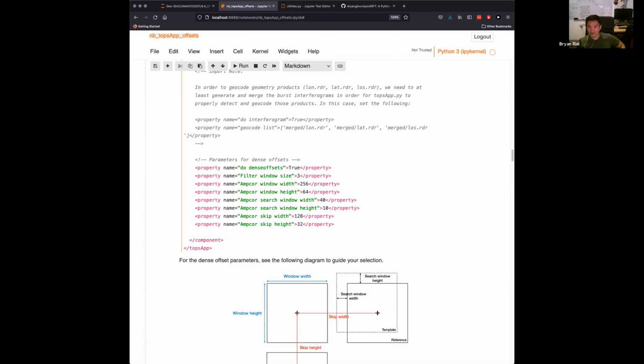What is the approximate? So the vector orientation for displacement is essentially just 90 degrees from your look direction in range. So if you look at your heading angle, that's essentially your azimuth orientation, and you can say your incidence angle is essentially flat along the surface. So that would be a 90 degrees incidence angle. That's one way to synthesize an azimuth look vector from look vector components that you have in range.